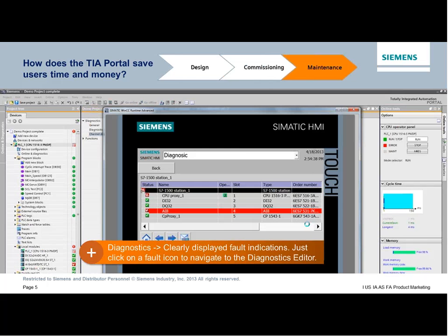So in other words, if somebody runs a forklift over a conduit and suddenly we've got a machine down situation, what TIA gives us is, since we have this common database and the diagnostics are throughout the project, we can have the capability of somebody out on the plant floor, rather than having to go grab a laptop and plug in with TIA Portal and so forth. All these diagnostics show up everywhere on the system. So we can lower the technical requirements of somebody to be able to fix a machine and get it back up running quickly.